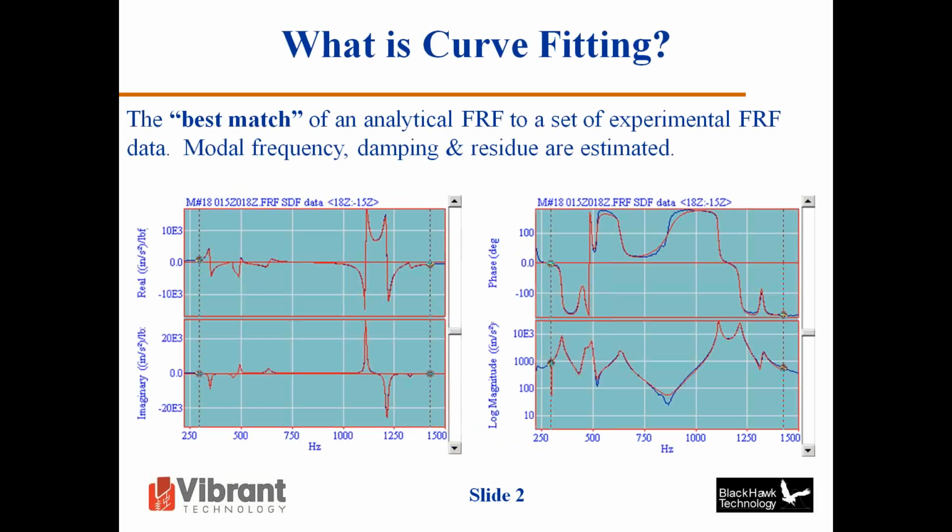So this is what we mean by curve fitting. Here's an FRF in 4 different formats. On the left are the real part and the imaginary part of the FRF, and on the right are the phase above the log magnitude. Sometimes the left hand is referred to as a coquad plot, that coming from the old days of sine testing, where we talked about the coincident and the quadrature wave, that being the real part and the imaginary part of the sine wave. The one on the right is often called a Bode plot.